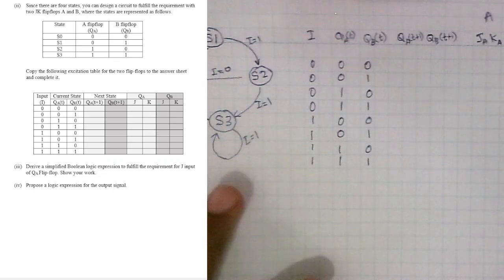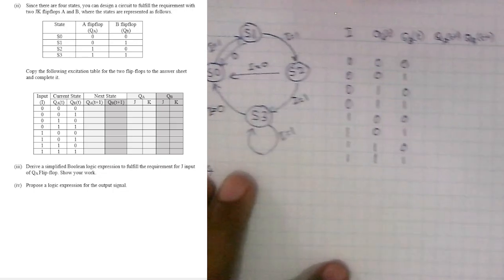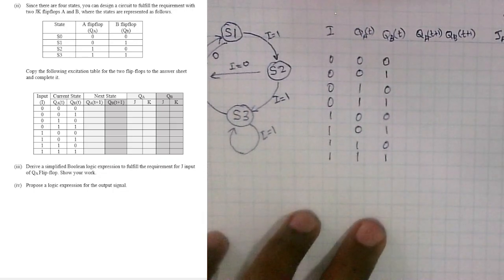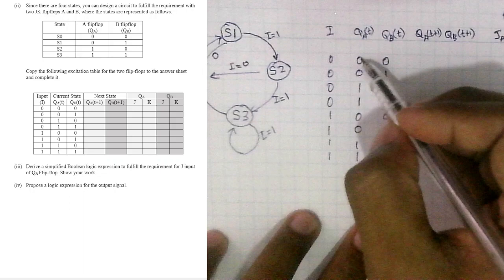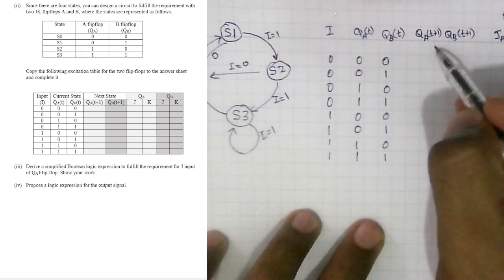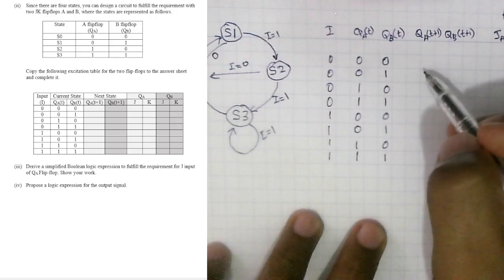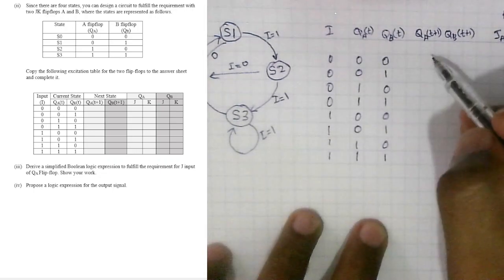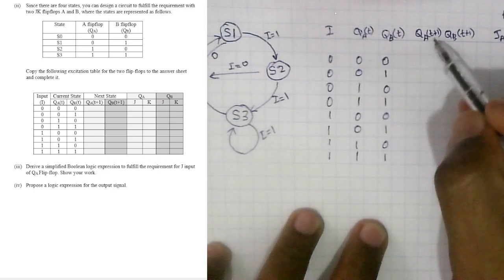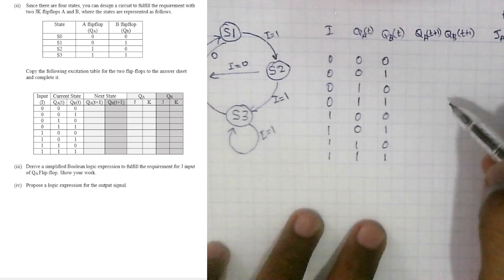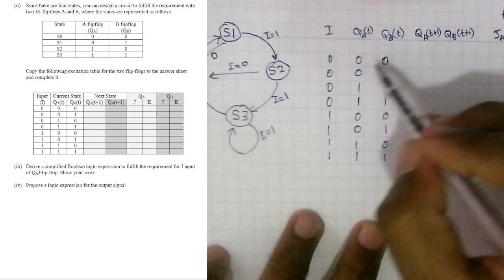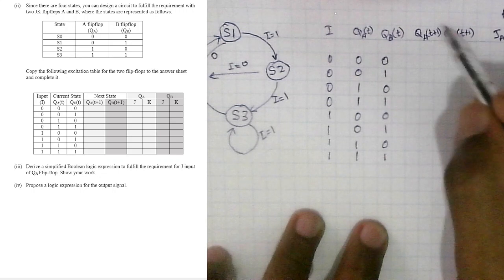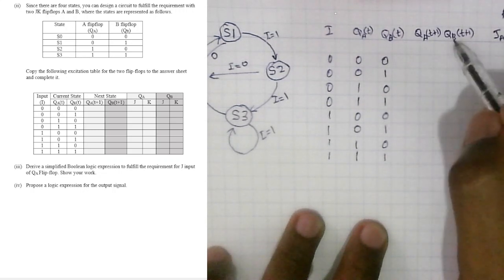Now you know the logic from here, right? And actually you can now determine what is the current state and what is the input. Based on that you can go to the next state, right? So that's the idea. Now we have made our state assignments such that 0, 1, 2, 3 are corresponding to the 0, 1, 2, 3 of QA, QB, right?